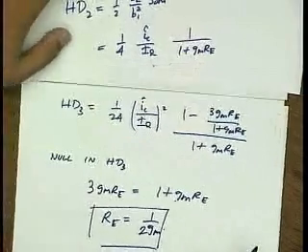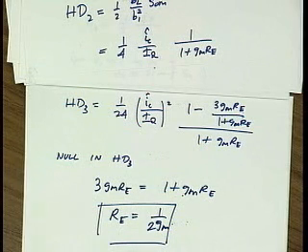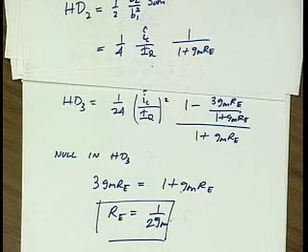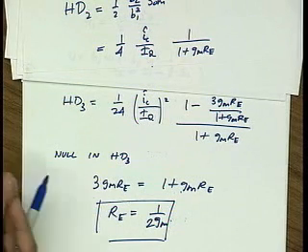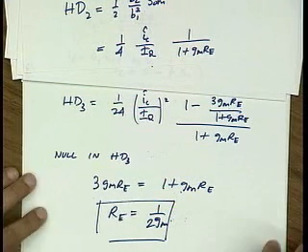So if, in theory, I put an RE which is basically 1 over 2 times GM, I'll get no cubic distortion. Now you can see the problem, because GM varies as a function of temperature. So if I get perfect distortion cancellation at one temperature, I change the temperature a little bit and RE has to change. Of course, it's not going to, so I don't get a distortion null.